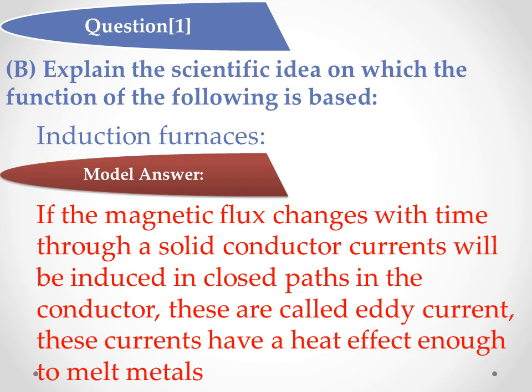Question 1. B. Explain the scientific idea on which the function of the following is based. Induction furnaces. Model answer. If the magnetic flux changes with time through a solid conductor, currents will be induced in closed paths in the conductor. These are called eddy currents. These currents have a heat effect enough to melt metals.